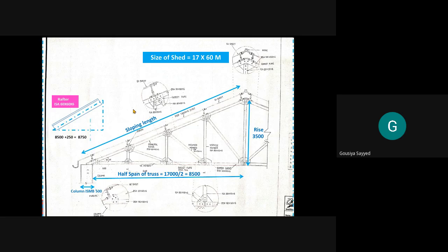Similarly, you can draw this vertical strut center line, and the distance between these two vertical lines is nothing but the spacing of the purlin. In a similar way, you can complete this diagram by showing the angle section widths and their thickness. So we can get this diagram.